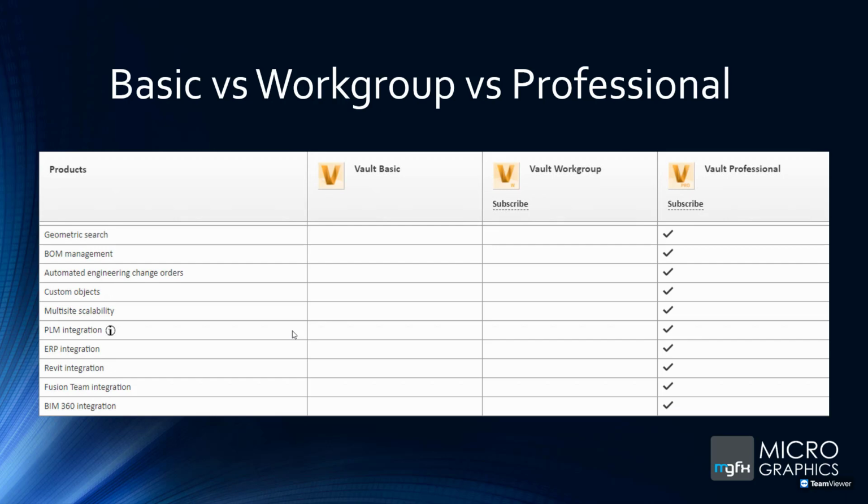Now, this is actually fantastic. One of the scenarios we went through was that sometimes you need to make a copy of something, but you can't find it. So what happens? You just create a new one. Oh, I know what this part kind of looked like, and I just create a new one and give it a new name. Now, the problem is if you do that 30, 40, 50 times, and now you've got the same part sitting in 50 different assemblies, that is just a waste, because if that part changes, you have to change it in 50 different places.